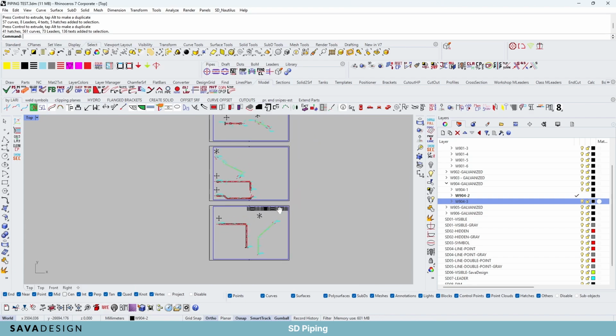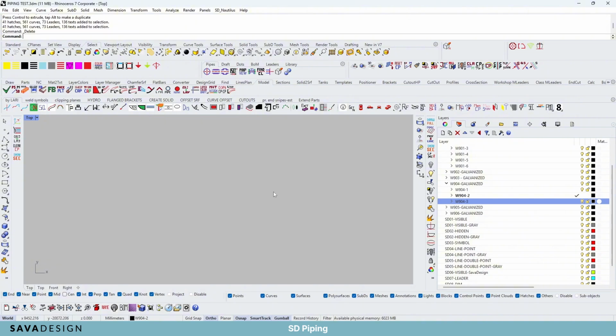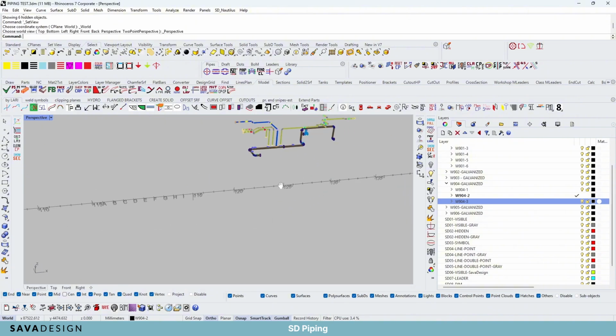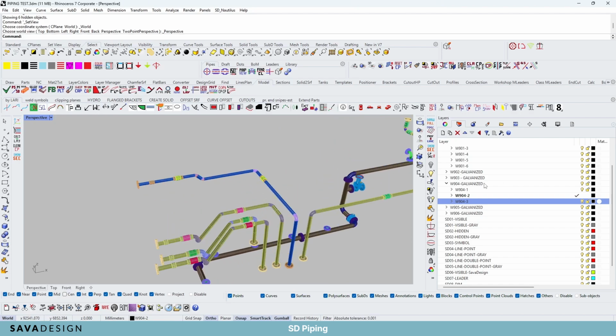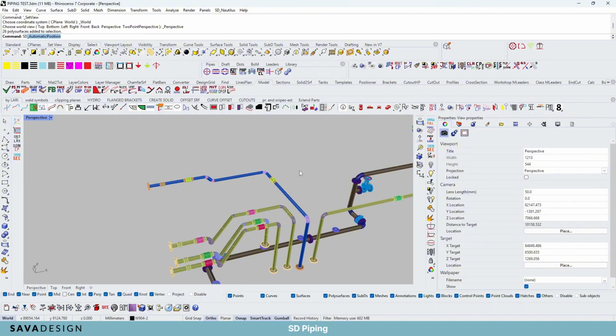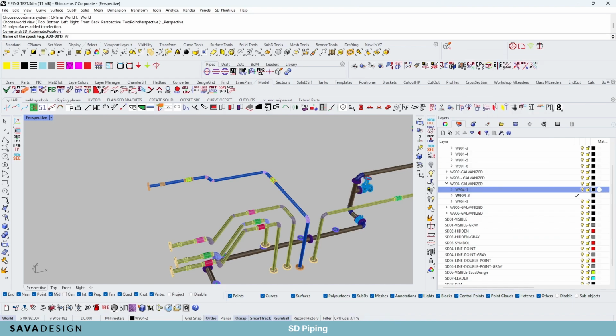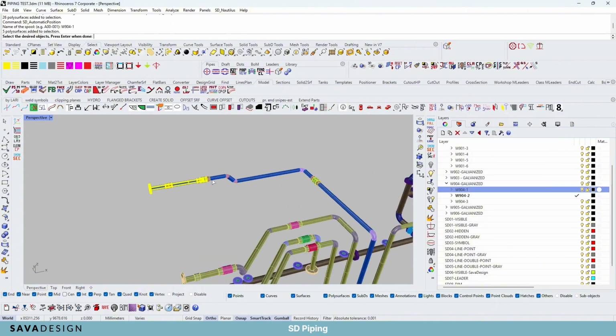Okay, so this is basically that process that we talked about at the beginning, so that you can model out a pipeline, you can assign the positioning, and you can generate basically CAD-ready drawings directly within Rhino. Now, Voya wants to see what we didn't position. I think we probably missed one element here or there.